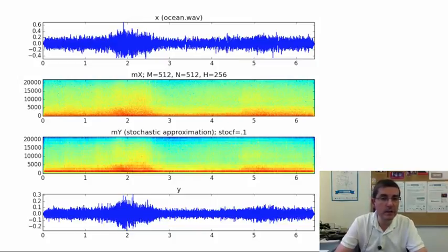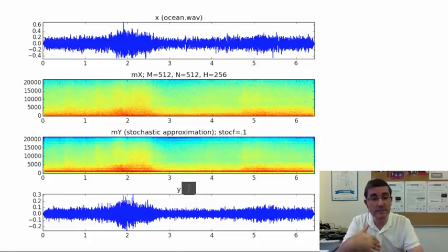In fact, here we used a compression of 0.1, so every 10 samples of our magnitude spectrum are reduced to 1. That's the idea of the approximation. Then we can synthesize by combining this magnitude spectrum with random numbers. So let's listen to the synthesized result.